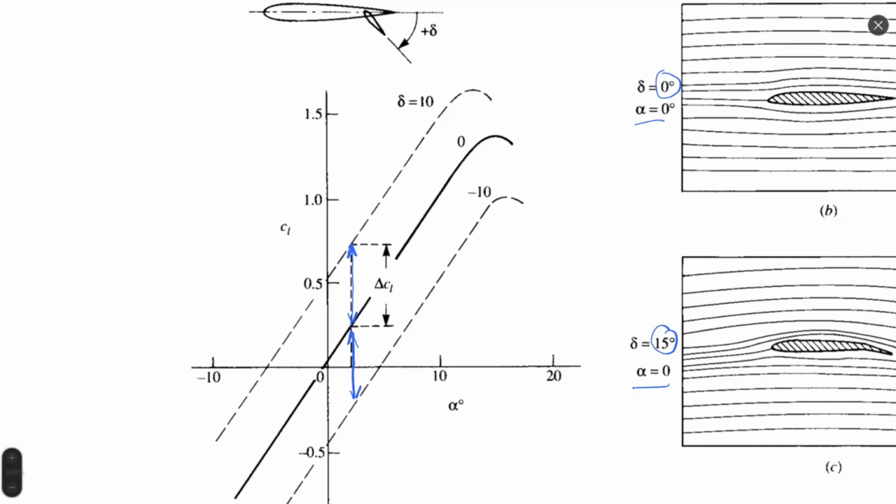So once takeoff is realized, we need more lift. Our angle of flap inclination will be positive, creating some additional lift, so we can take off at smaller velocity. Then during the flight, flap angle is close to 0.